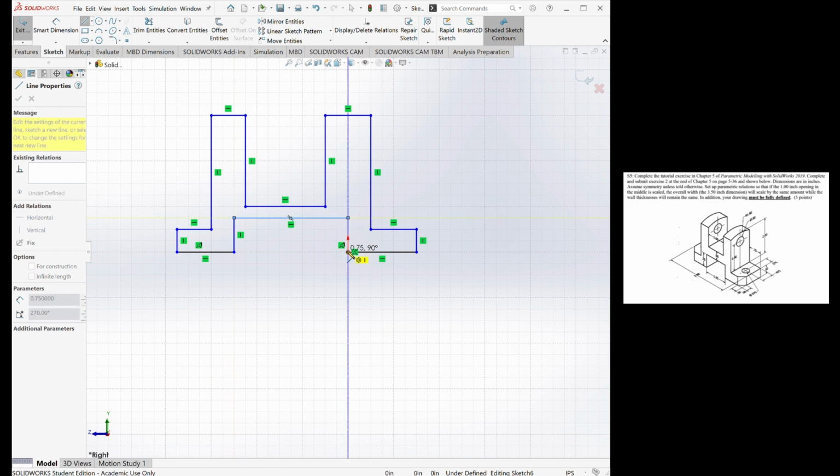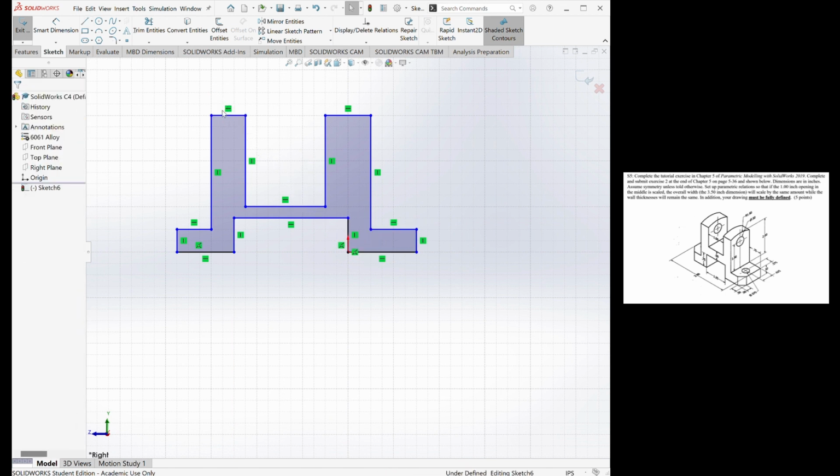And then you're just going to go through and sketch a very broad shape. We are not going to care very much at all about getting those proportions right. We just want to make sure that all the lines that are supposed to be in line with each other are, and those that are not, are not, because otherwise that can mess things up, because SolidWorks will apply extra constraints that don't apply to your sketch.